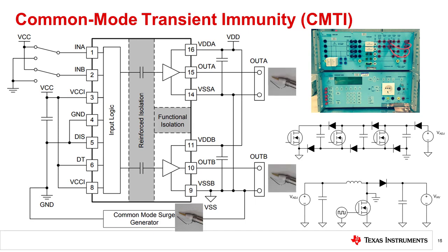The CMTI test should be designed so that the driver output grounding point is always tied to the same ground as the oscilloscope. Floating the driver ground apart from the oscilloscope ground requires using a differential probe or an isolated probe, but the poor common mode rejection of fast high voltage transients leaves most differential probes with noise larger than the desired signal, and isolated probes with the required high common mode transient immunity are very expensive.